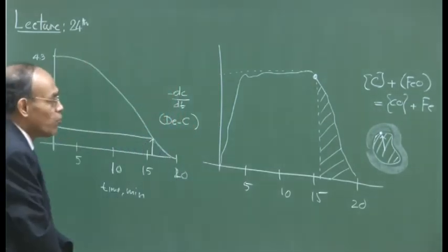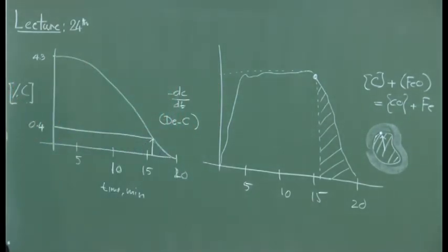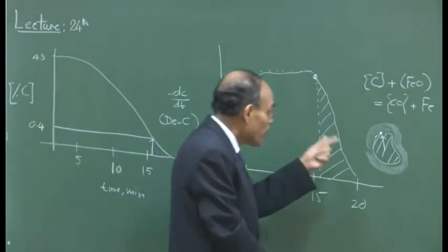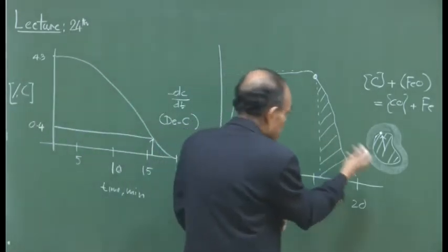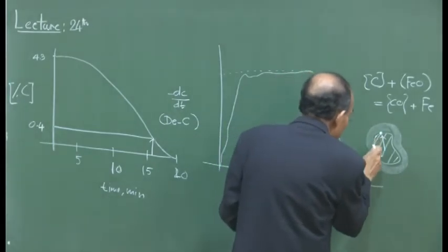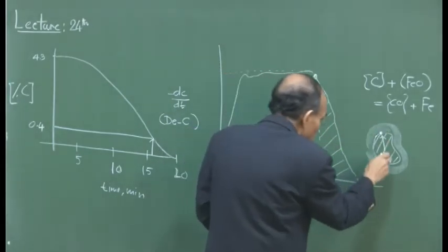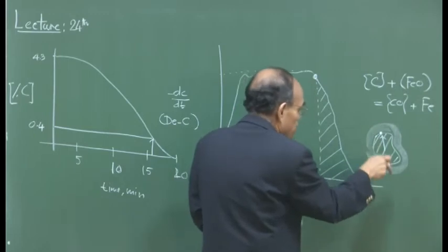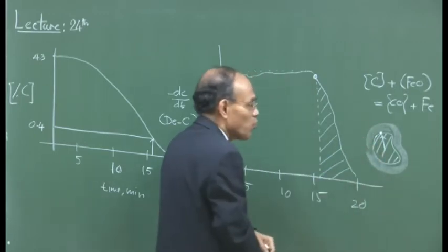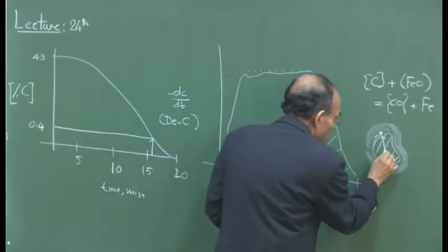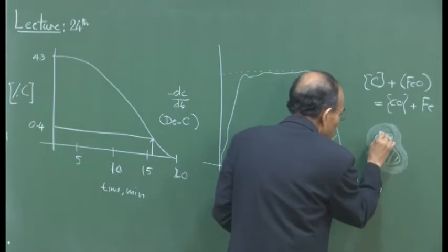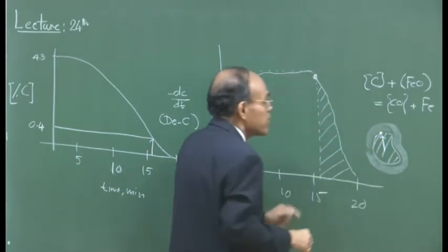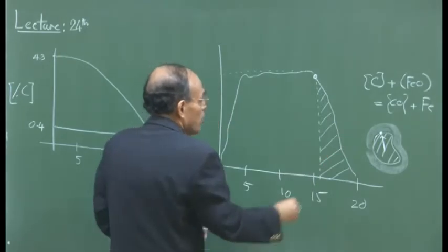If you are talking about steelmaking conditions, it is not a solid liquid mass transfer, it is a liquid mass transfer, but still you have a boundary layer within the liquid side, since I have said categorically that it is a melt phase transport control. So, from the bulk of the metal, the carbon has to reach this surface, and there possibly this reaction takes place.